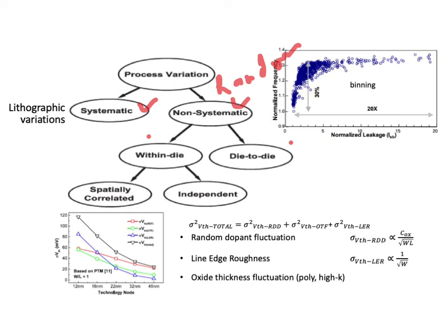So these refer to die-to-die variations, and they are a little simpler to handle because you can characterize individual dies. A die is just a single product, a single IC. So if you have the whole wafer, you could characterize the dies at certain parts where they are faster and sell them as a faster or higher-spec device, versus the dies at the edges that tend to have poorer performance, which you could sell as a lower-spec device.